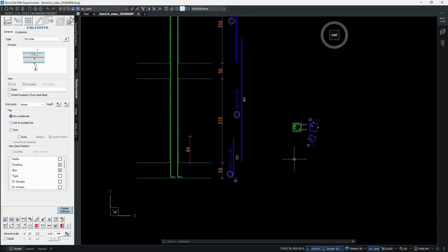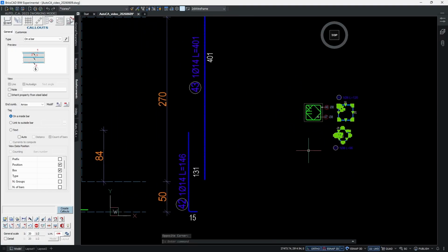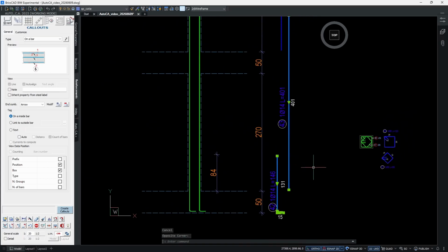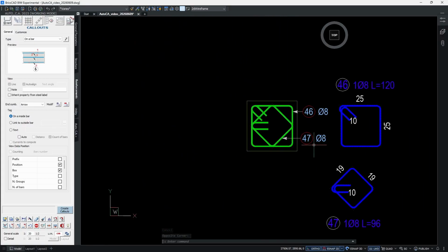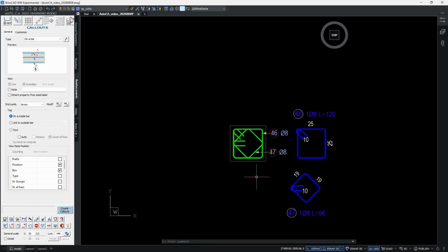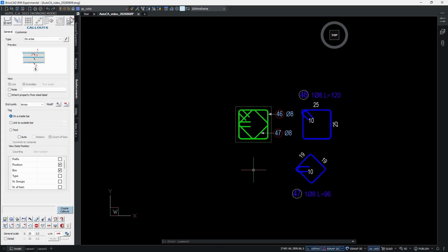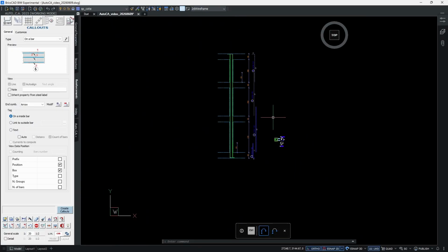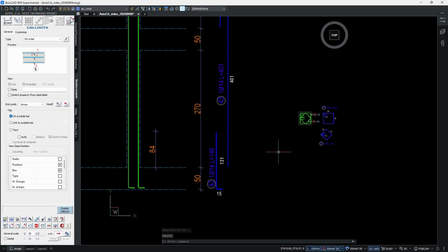You must link these stirrups to a column distribution and the longitudinal bars to the section bars. This is how the program calculates precise quantities. And we use the modify command to achieve this. And note that for column reinforcement, as in all other cases, all these entities function as macros. So they are freely modifiable and reusable at any time.